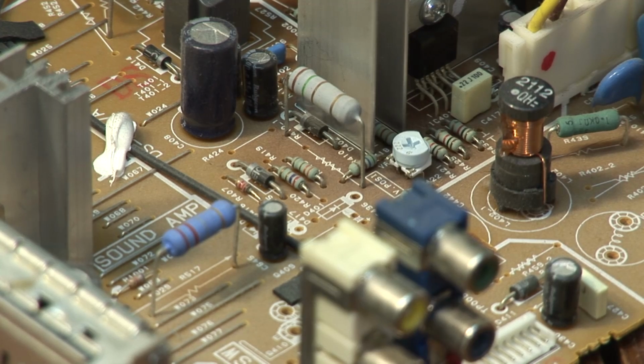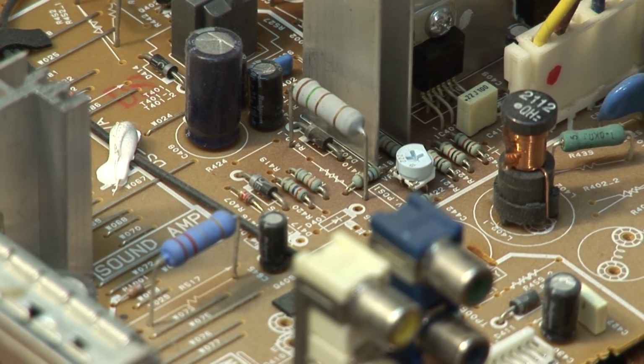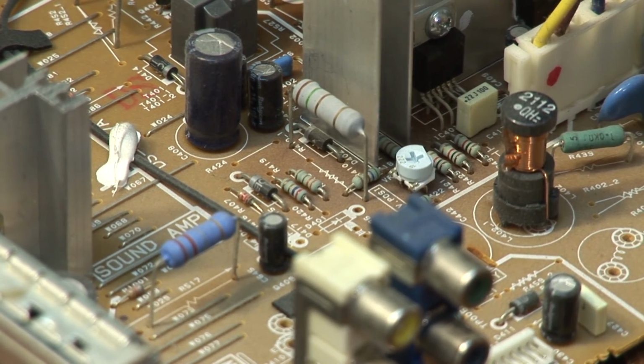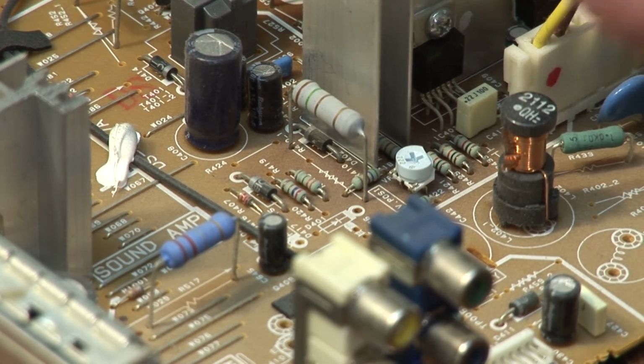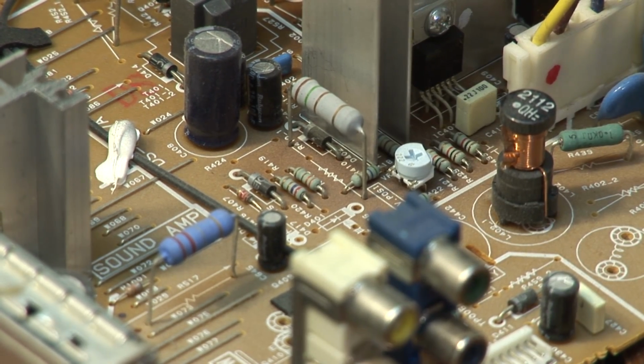It's a capacitor called a bootstrap capacitor. Seen it a zillion times on Toshiba. Never worked on this particular model of set before. So we're going to get in here, we're going to use some test gear and look at the vertical pulses going to this vertical output IC.